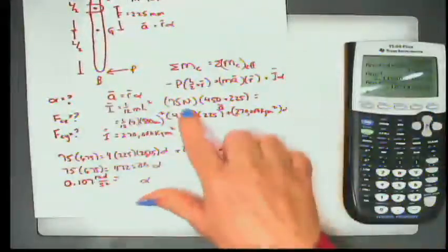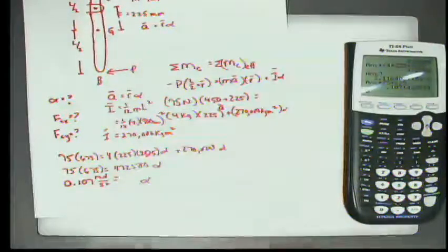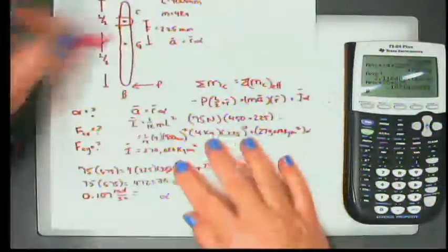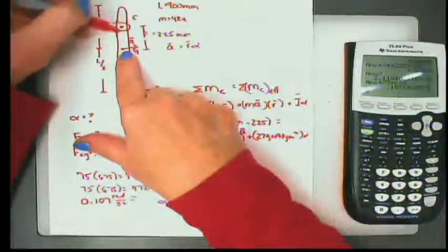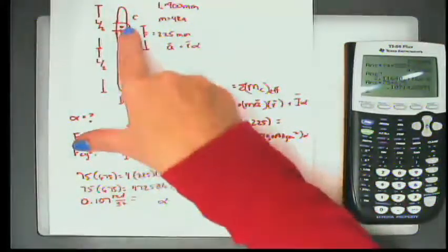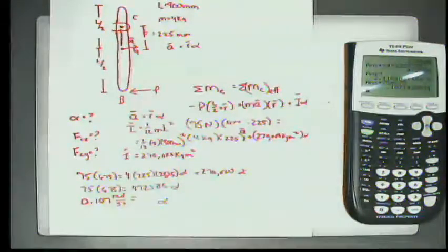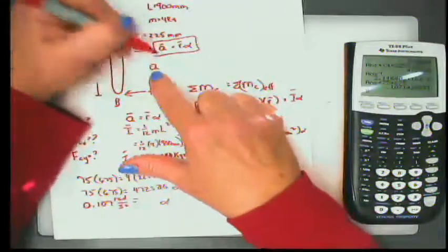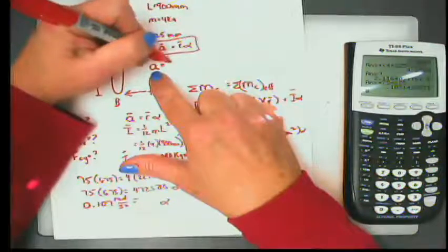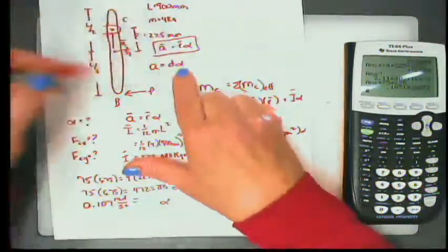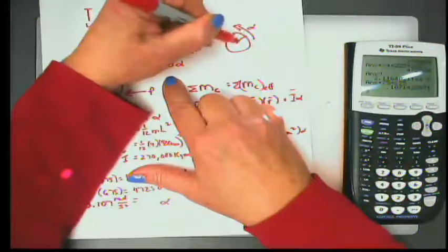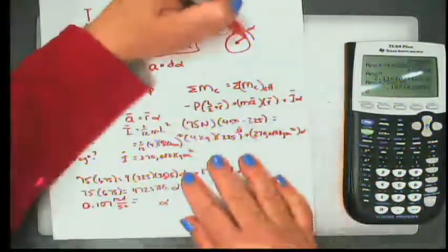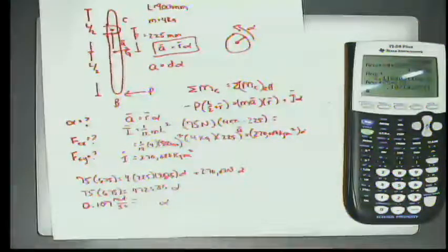Yeah, I dropped something. Talk to me. I need to change these into meters. I can't work with that in millimeters. Does that answer your question? I was going to ask you where you get the 225 alpha from to substitute A bar. Yeah. If you look at this, A bar is the vector here, right? The acceleration of the mass center. Well, it's pivoting. All of that is pivoting about C. It's kind of like a moment there. Yes, it's exactly what it is. It's I bar alpha. This is just if you have a pure rotation. In a pure rotation, linear or translational acceleration is equal to some distance times alpha. So in any sort of rotation, if you know the angular acceleration about some point, and you know the distance between that point and some other point, you can find the acceleration of the second point in a translational sense based on that.